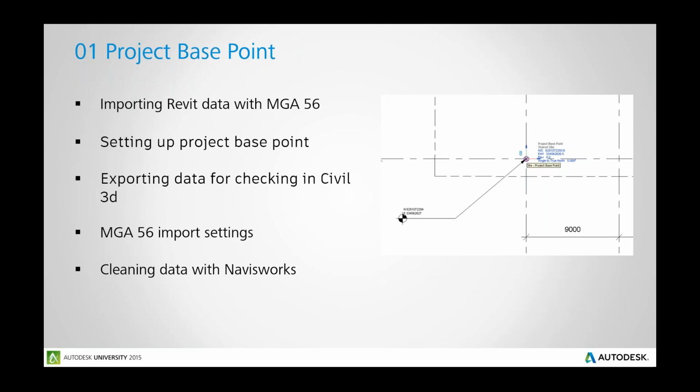and the coordinate systems. And then one final option, if you are working with other file formats, is to bring it into Navisworks, use those tools to reduce the amount of data, clean it up using the polygon count tool. You can reduce that and then bring in those large gigabyte models, not terabytes. You can bring them in, but Navisworks is a great tool for you to reduce that polygon count before bringing it into Infraworks 360.